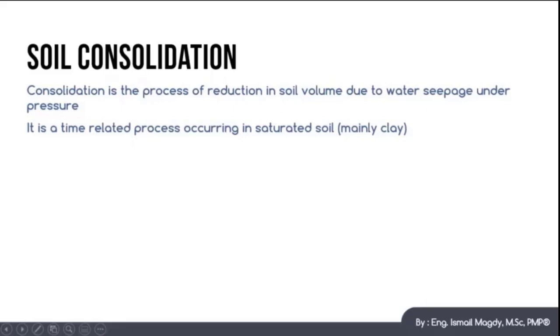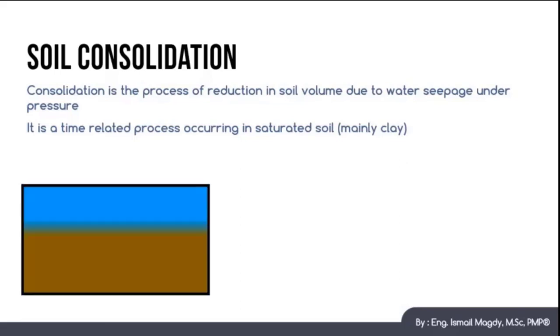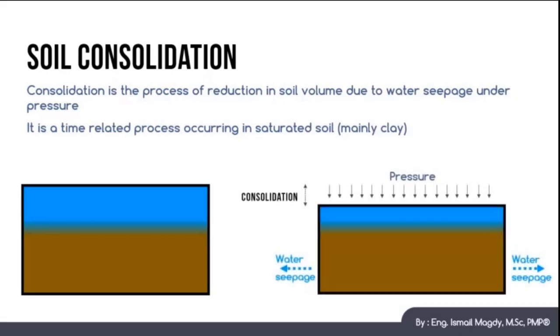Consolidation is a phenomenon that is associated with saturated clay soil, and it is the process of soil volume reduction under pressure due to water seepage. As we can see here, if we have this layer of saturated clay soil and we start to apply pressure on the soil, with time it will start to get compacted as the water escapes due to the seepage, and this will create settlement to the structure above the soil. So it is important to learn how to calculate this settlement.